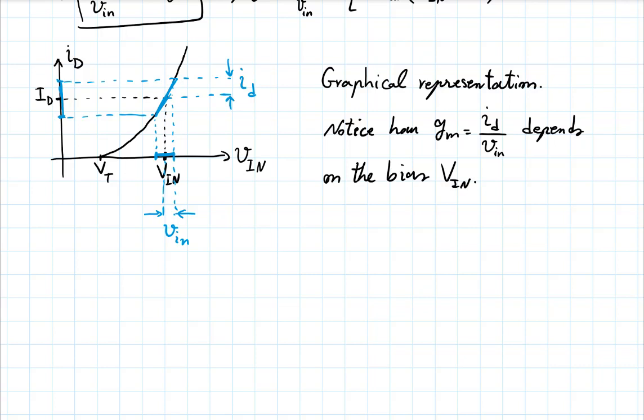You can do the same thing for the BJT. The difference is for the BJT, if you're talking about the collector current versus the base input voltage at the base, if you are in its active mode, the formula is not a quadratic equation, it's an exponential equation, right?